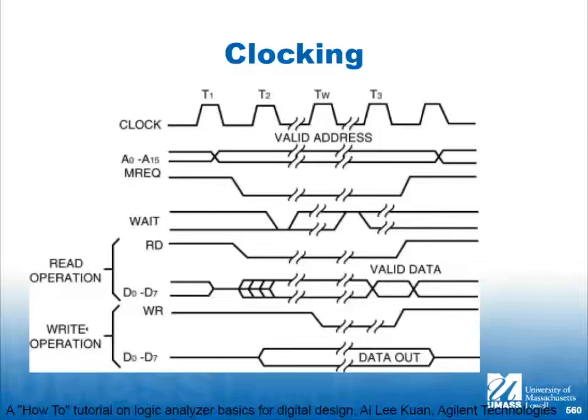So back to my $80 or so USB oscilloscope, it has 16 channels of logic analysis, but I found out after I bought it, not that $80 was a lot, that the logic analyzer doesn't have an external clock input, which means it uses the oscilloscope time base for the logic analyzer. With that said, it has a lot of memory in it.